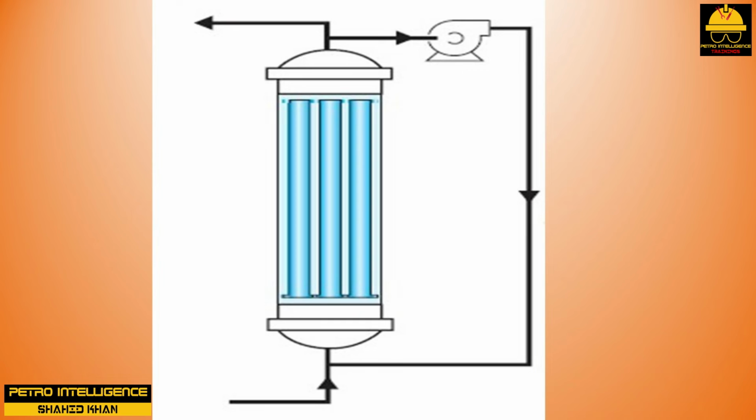The considerations in designing a tubular reactor are the heat transfer surface required to maintain the reaction temperature, the tube volume needed to produce the desired amount of reaction and production rate, and the tube size needed to give an acceptable pressure drop through the reactor. Tubular reactors are needed for chemical synthesis.